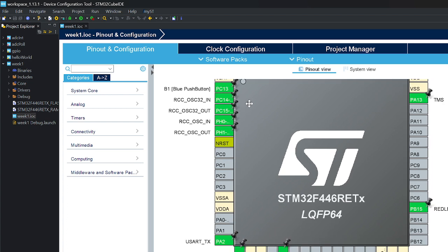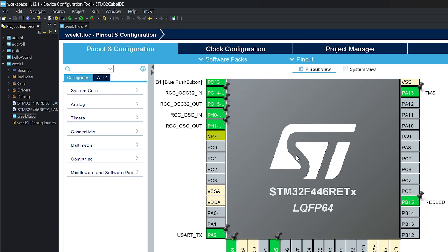Is there any reason to use set or reset rather than just toggle the pin? If you're just wanting to flash a light, toggle's great. But if you want more control over it, then you can specifically say, I want to write something, I want to clear something. When we set up things, for instance, when we set up our TFT, you're going to be needing to enable a chip select line and be able to pull it high and low, and at different times you would use the sets or the clears. If I just had a light blinking, I'd just use toggle.